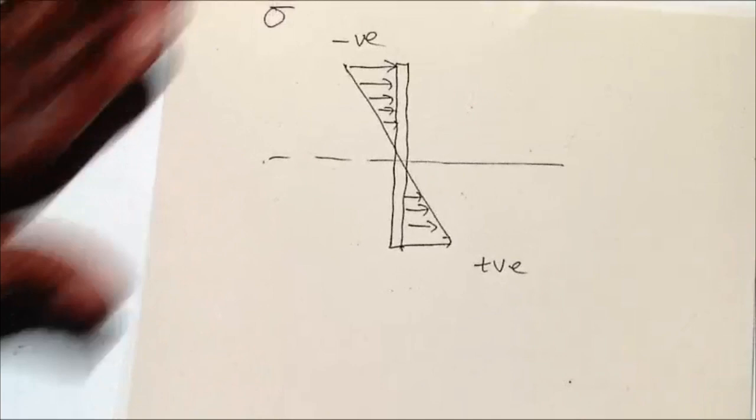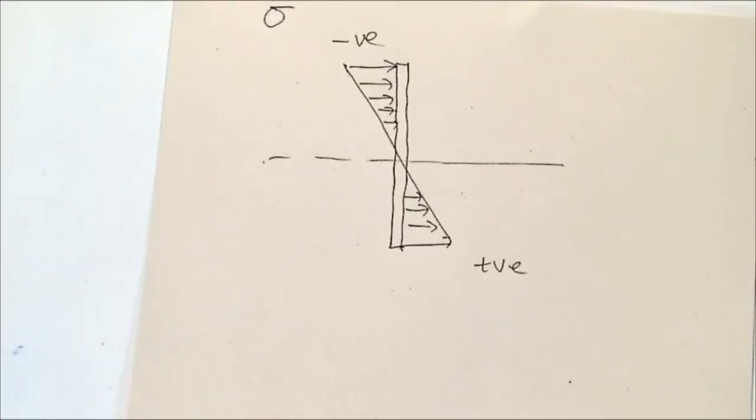So that is the stress along the length of the beam, acting along the length of the beam. But we have not applied any load along the length of the beam. We are only trying to bend it. But we are generating stress along the length of the beam. In order to ensure we have equilibrium, because any internal stresses you develop must be in equilibrium with whatever load you are applying on the structure.